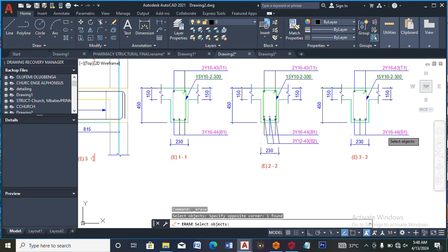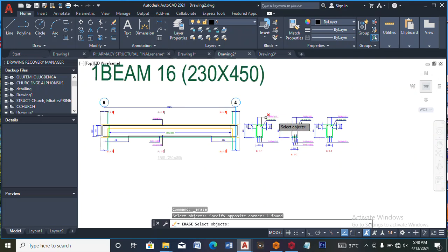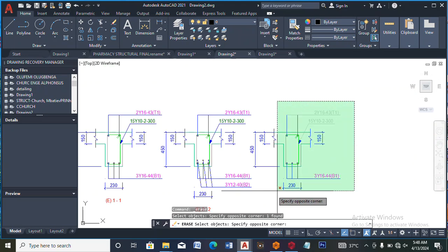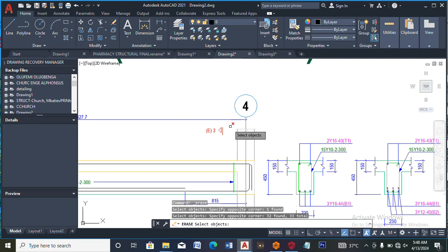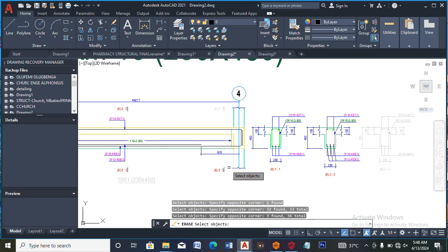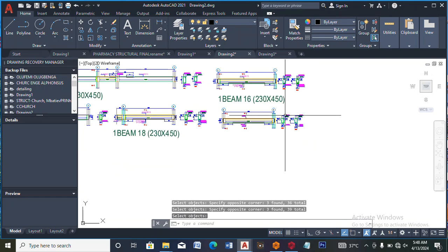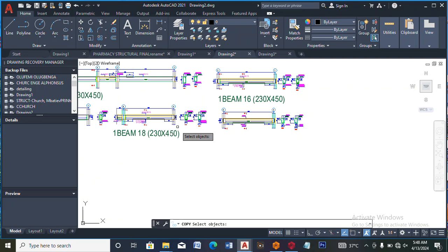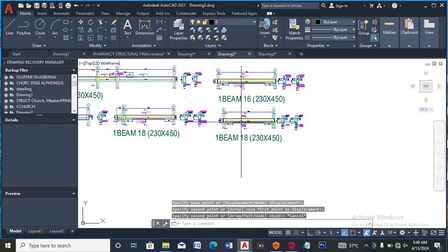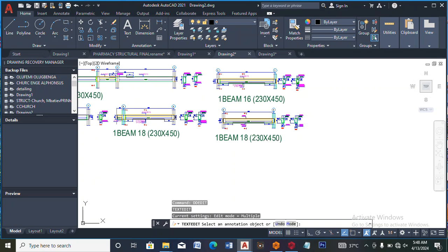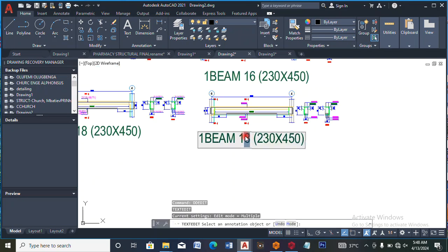3Y16, 3Y16, 2Y16 top, 2Y16 top, to this section. If you want, you can actually leave the three of them, but for space, for it to accommodate more details, I will have to remove that one. And so I have this as B19.